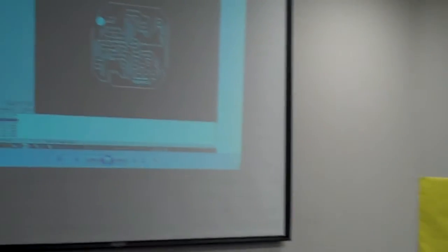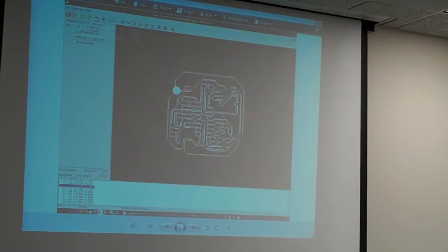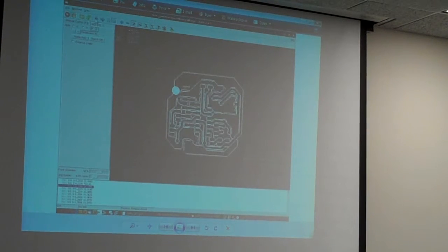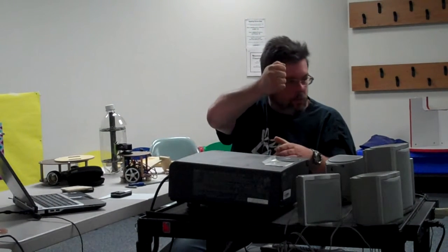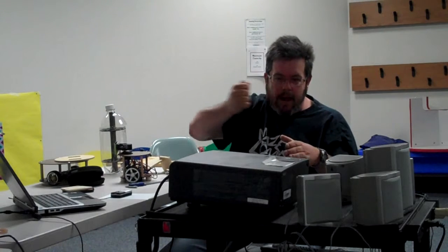Warren? This has a preview thing, so we can see the tool head moving here, couldn't we? Yeah, I can't now. I don't have Linux on my laptop. But if I was downstairs at home, I could turn the machine off by hitting this, but then still play the file, watch it step through everything. If you're real paranoid, say you're cutting a piece of really nice wood or something, you would do a dry run first on the screen, then you would home your axis way up, and then let it run through and cut the air, make sure there's no errors, and then here's this nice piece of oak or whatever, then finally home it and cut it for real. But most of the stuff I do, the hardwood, if it makes a mistake, I just throw it away and start again on another one.